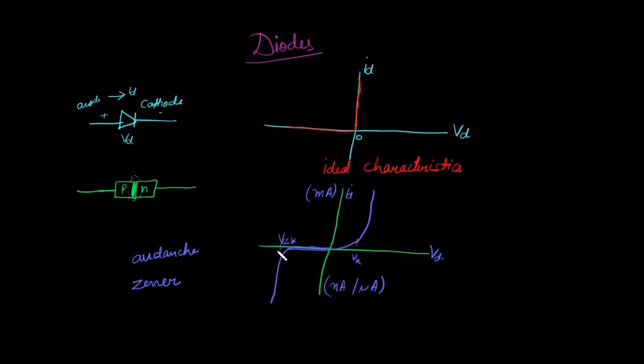In the avalanche effect, due to the reverse bias potential, the carriers moving across the PN junction acquire so much kinetic energy that they hit the crystal ions in the transition region. This is the transition region.